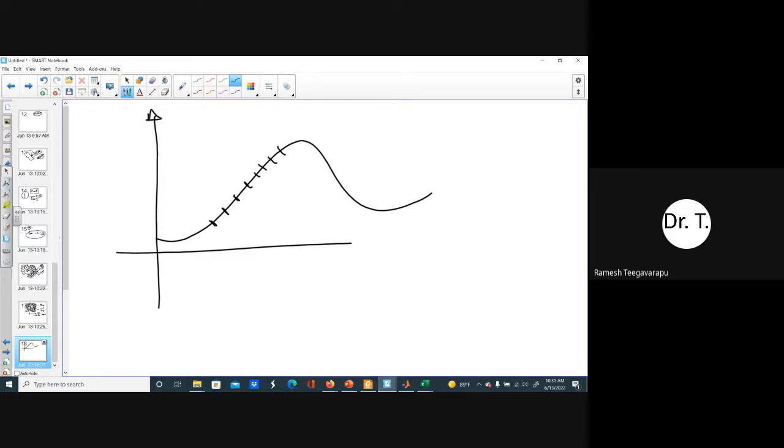So, for example, the ups and downs. In this case, if I have a linear line, high values follow high values, and so on. So the persistence of a linear line is very high. The persistence of a hydrograph is also very high because the current value has a strong dependence on the next value. That is called persistence. If you remember, correlation is between two quantities. Autocorrelation is the correlation onto itself, but by different lags.